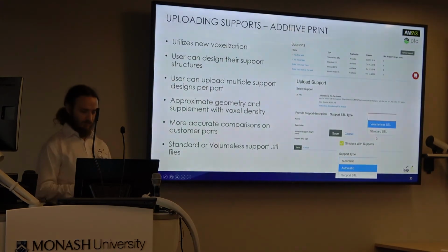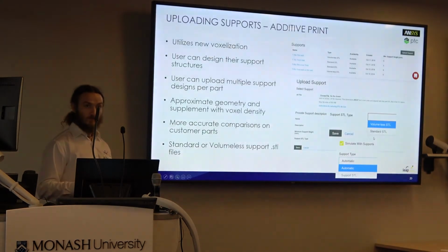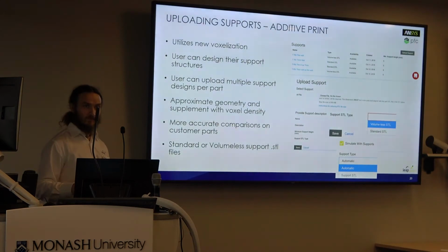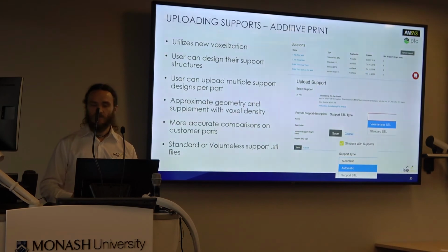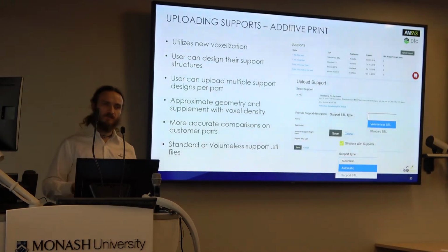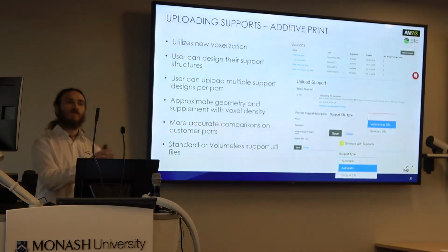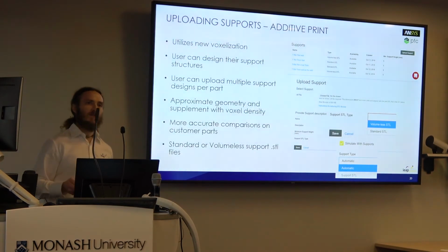Sorry, are those voxels treated as elements in the solver? They treat it as elements. Yeah. They're more like an Euler representation, where they can have a combination of material or void. So it's not quite the same as an element.